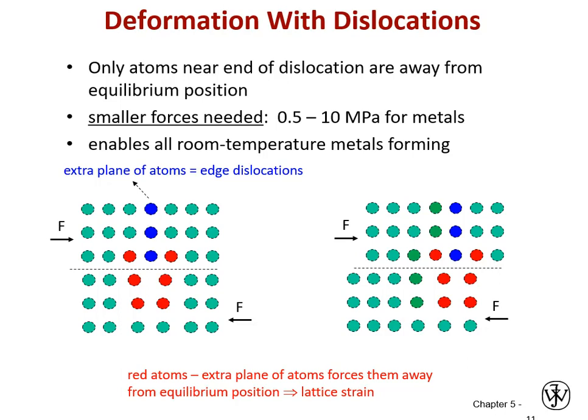But this time we don't have to move every atom. We only have to move the red atoms. And not only do we only have to move 6 atoms instead of a semi-infinite number, well, 6 in this cross-section. This is a plane going infinitely into the screen, remember. These are also already in a somewhat higher energy state. So we have 2 benefits going for us. We don't have to move as many atoms, period. We've changed it literally by 1 dimension. We don't have to move a plane of atoms, we only have to move a line of atoms.